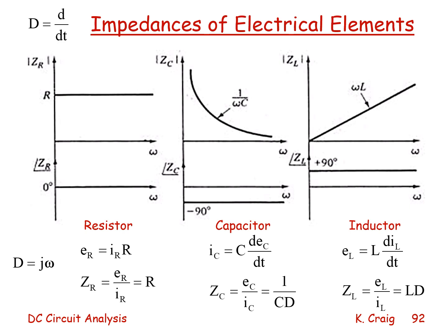So here is a diagram summarizing what we have just talked about. I'm using D as my differential operator, and to get frequency response, I let D equal J omega, where J is the imaginary number. Sometimes we use I, but we don't want to confuse it with current. For a resistor, the magnitude is constant, it's R, the phase angle is 0 degrees.